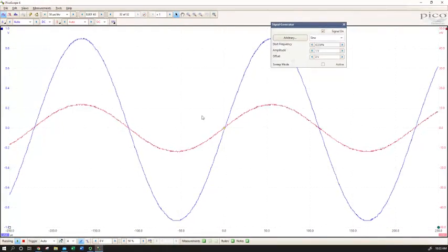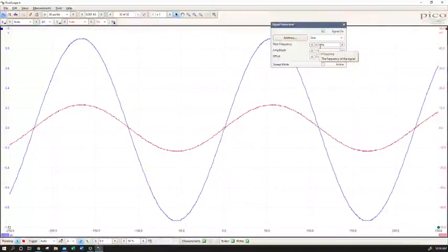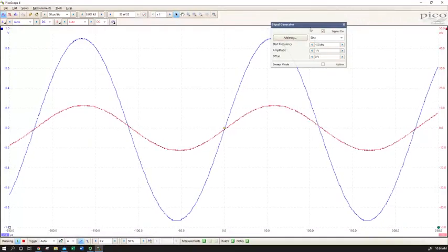Why am I getting a different value today? Hard to tell. Some of it could just be difference in the way I have the circuit hooked up. I could have some inadvertent additional capacitance or inductance. You can see depending on exactly how you call this point, I may have overshot and now be lagging with the resistor versus full circuit. But it's close. It's between 0.2 and 1/4 of a Henry. So I at least have it within about an order of magnitude.